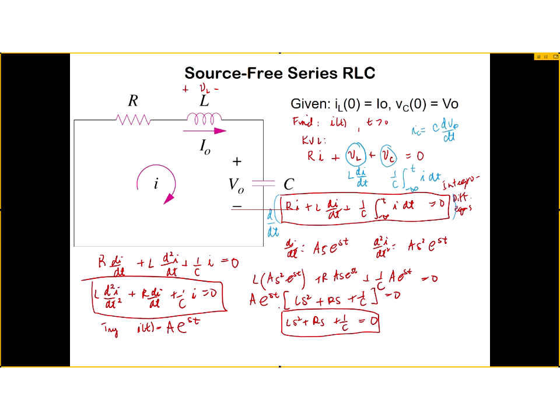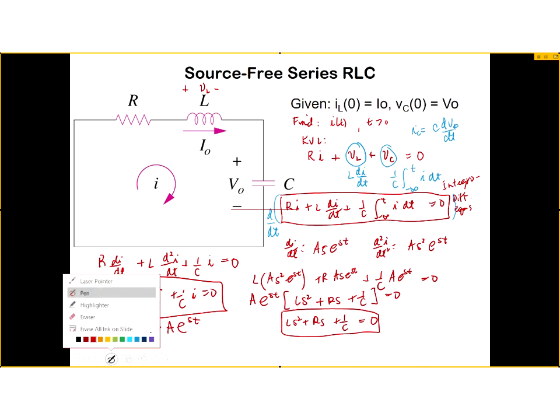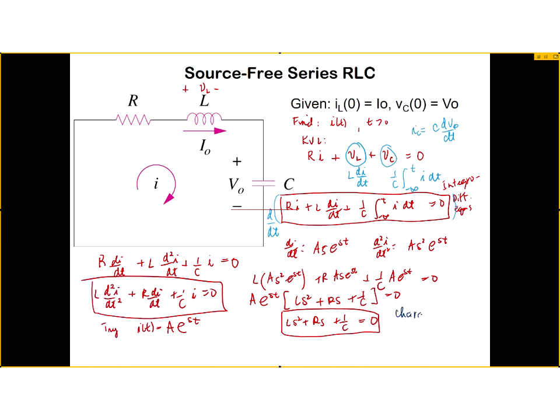Yes, we're going to have to use a quadratic formula. And take note that this equation here in differential equations is what you call the characteristic equation for the differential equation. Why is it called a characteristic equation? It just is. Well, in the context of our problem here, it really characterizes the circuit.